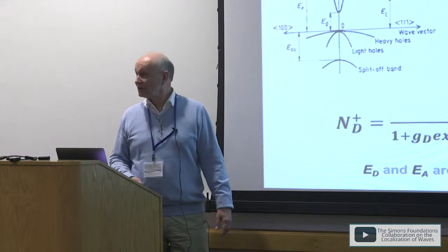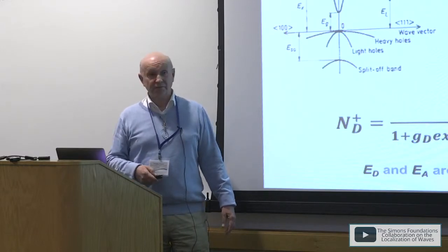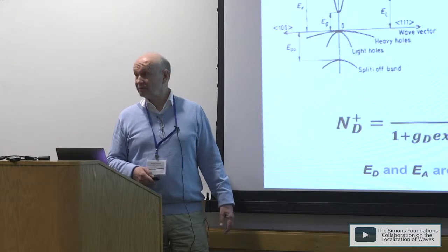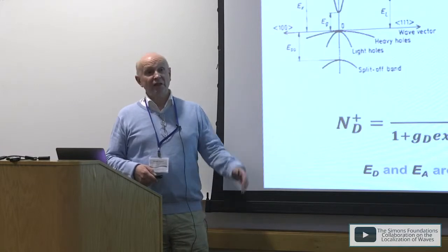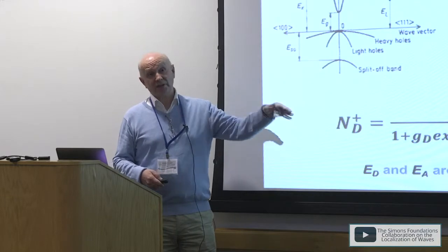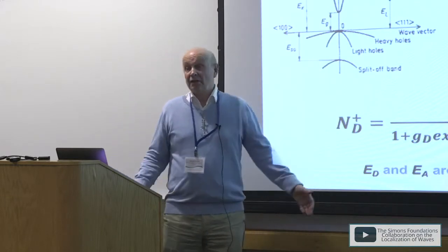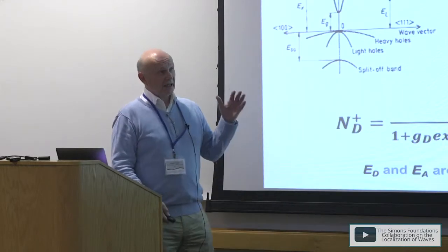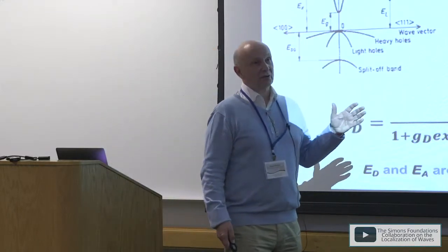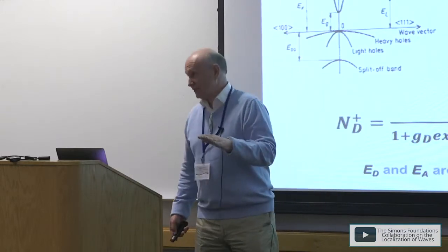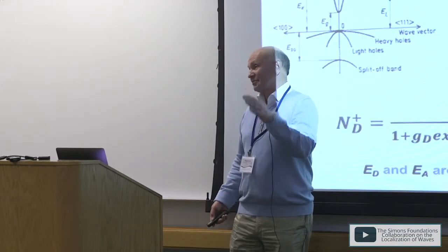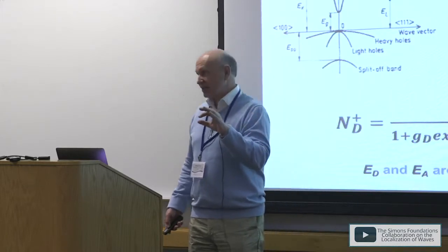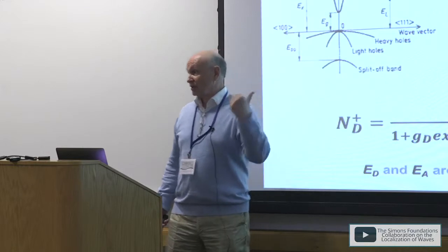Chris, are you talking about the static dielectric constant? No, the optical. And this has both, right? No, this is static. Well, but that has the electronic effects in it as well. Yes, that is the electronic contribution to the dielectric constant. Yeah, it is, and it may also be taken into account. In most cases, for instance for LEDs operating at practical current density, the contribution of free carriers is small.